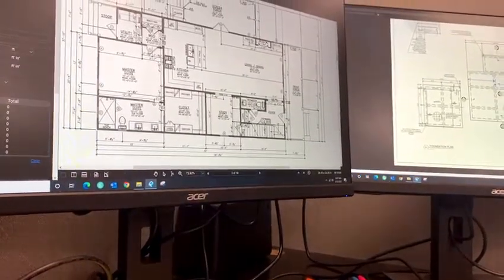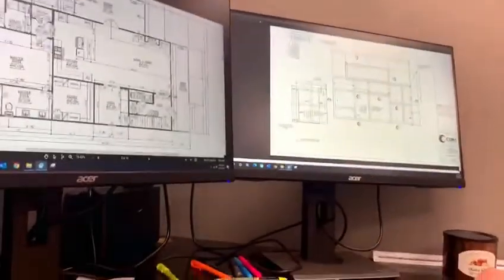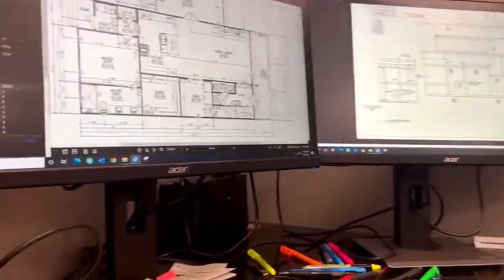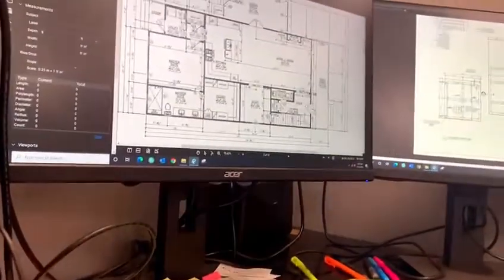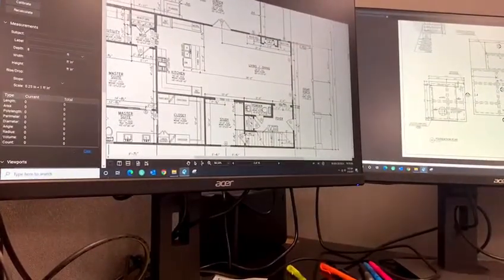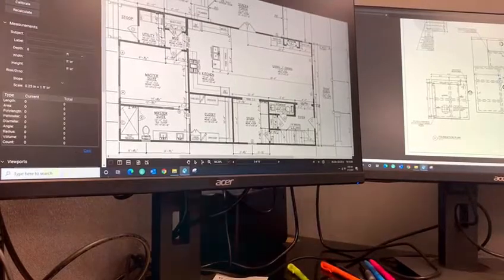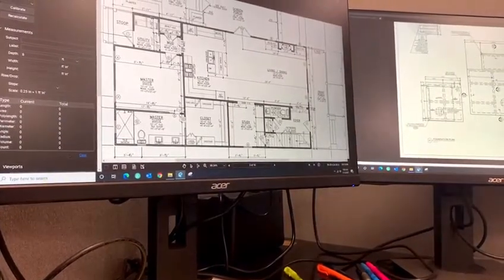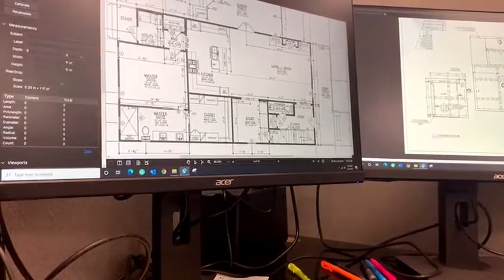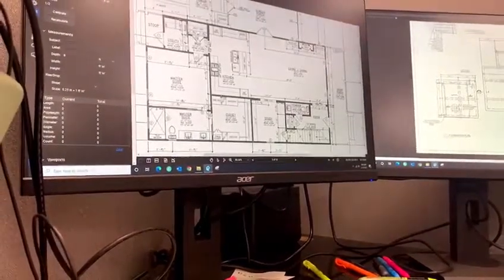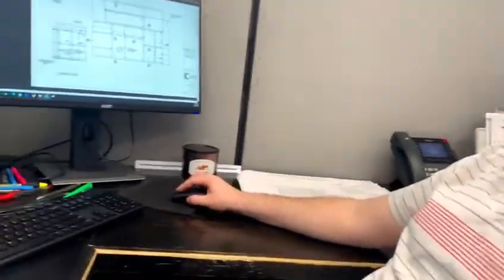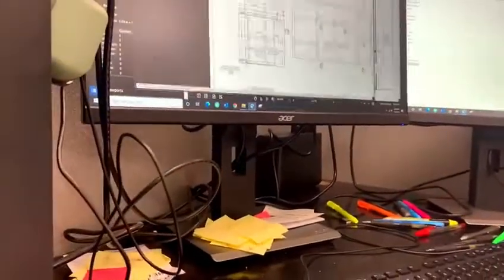But this is a preliminary design. Right, yeah, you have to be. Because that's normally where I place the interior grade beams, right? Under the proposed wall. Yeah, this is a preliminary design. We can make changes here. We could put a grade beam under here, especially since it looks like we're going to be running our framing. We'll get to that in a minute, but my first instinct would be to run something under here for support. Exactly. That's why I wanted you to open the floor plan, because I like to see both the foundation and the floor plan.